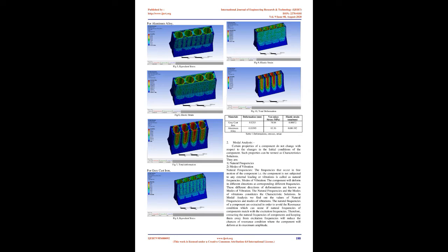Aluminum alloys. One of the key weight-saving elements in the engine design is the use of a cast aluminum cylinder block with cast iron cylinder liners. The cast iron liners, with ground outside diameter, are press-fit into the precision bored aluminum cylinder block. This gives optimal heat transfer into the cylinder block. The iron liners give the wear resistance needed for improved durability. The installation procedure for the liners includes cooling the liner prior to placement and refined precision force monitoring to ensure proper installation. After installation, the ID of the iron liner is bored to a mass-saving 1.5 mm wall thickness.